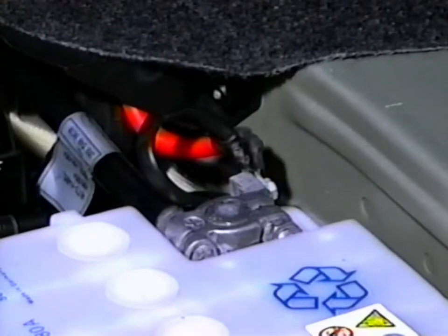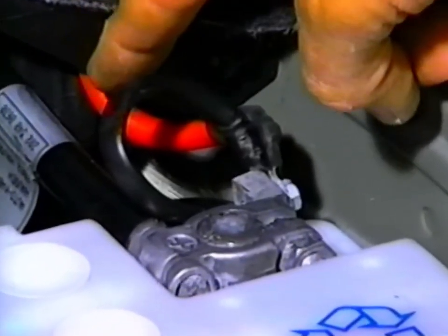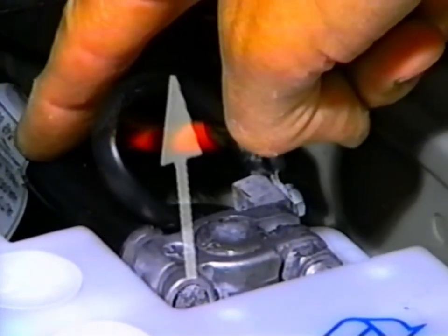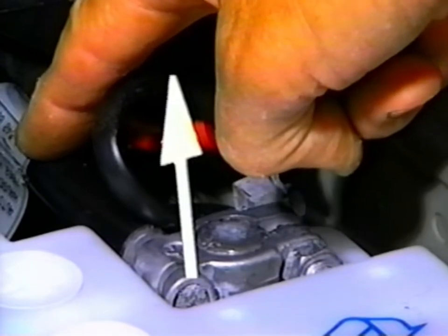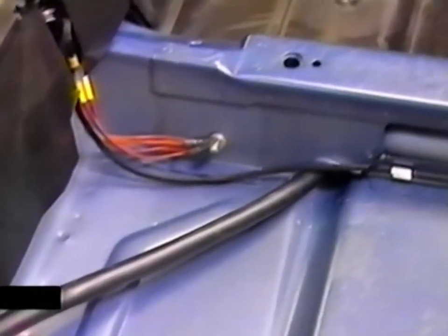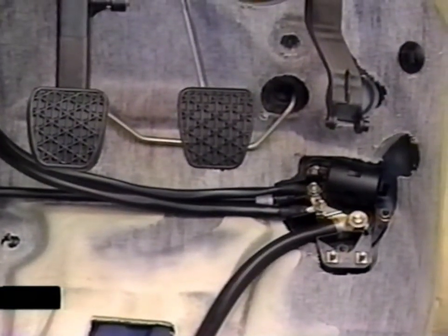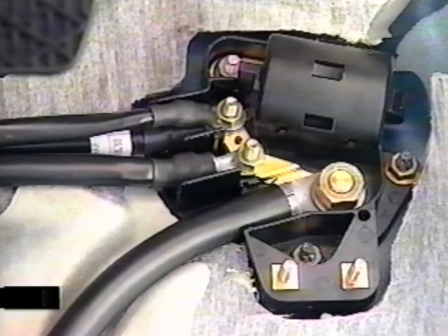There are several significant changes in the body and accessory system. To begin with, there are 3 battery positive cables. The small black cable feeds the rear fuse box. The large black cable is routed on the left interior of the vehicle and supplies all consumers except those fused at the rear fuse box, and the electronic control modules in the right side of the component compartment.